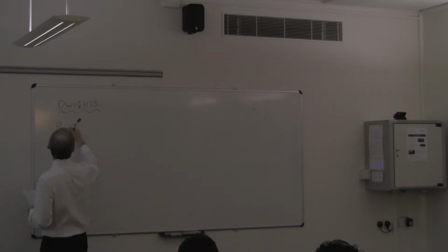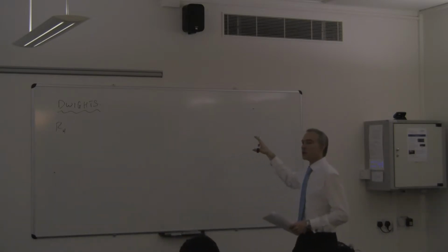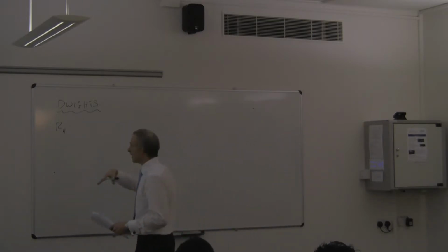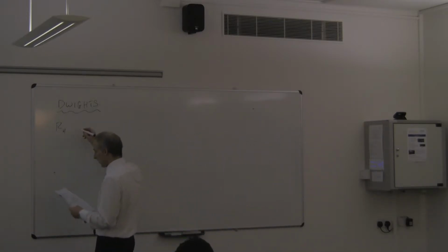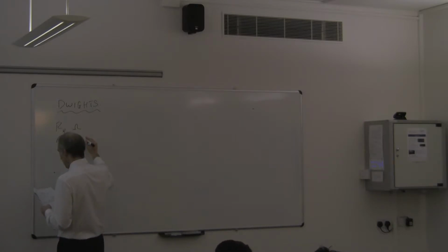Okay, so for Dwight's equation to work out how many anodes you would require to be placed on a long pipeline in a horizontal fashion, you need to know the resistance in ohms. Rho would be the resistivity, in ohm centimeters. L is the length of the pipeline.